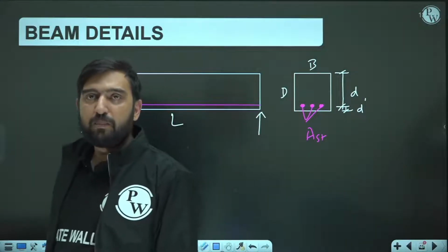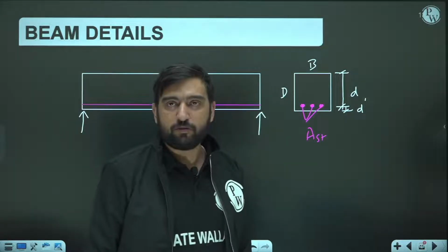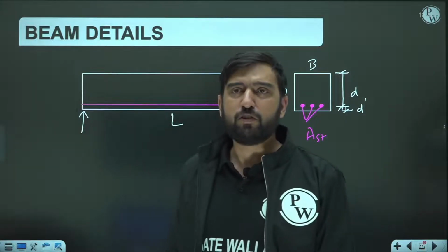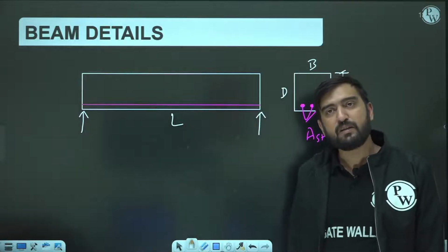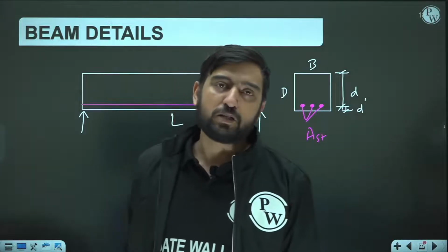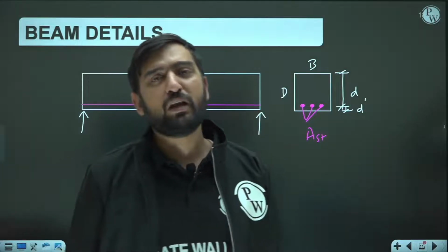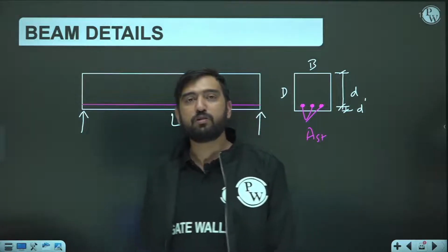In LSM, the partial factor of safety for concrete and steel was 1.5 and 1.15. Although in concrete, first of all, we have taken the 67% of the characteristic strength, hence we applied the partial factor of safety of 1.5. Similarly, on steel, we have provided the partial factor of safety of 1.15 because the reliability on steel was more, because quality control was better there.